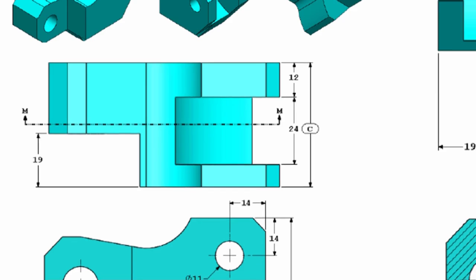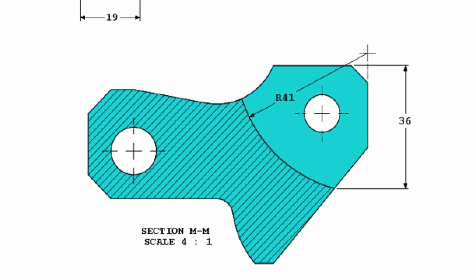Another item that is very often missed is the center point of the 41 millimeter radius needs to be vertical to the right edge of the part. If that sketch relation is missed, you have the potential of cutting too much or not enough material away, and that can throw off the mass of your part in your answer.